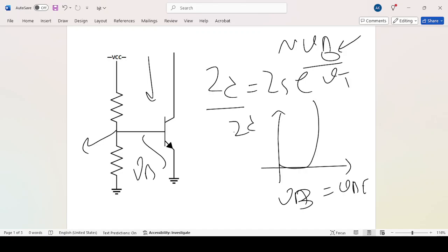It is a crazy type of behavior, and this is why we like it as analog designers. It would have better gain, better frequency response, and for example, gm over ID is usually better, so with less current you would have a better gm, then a better frequency response and better gain, everything.